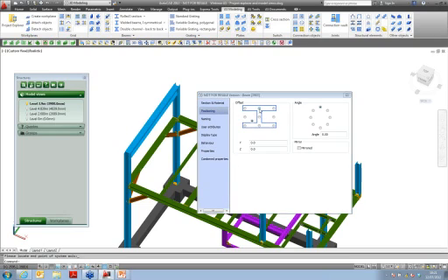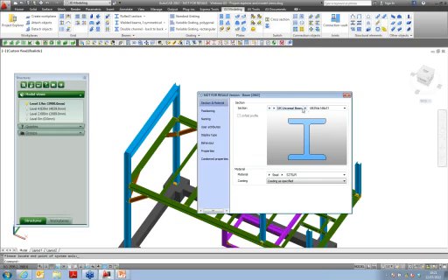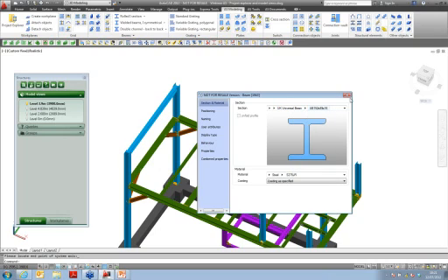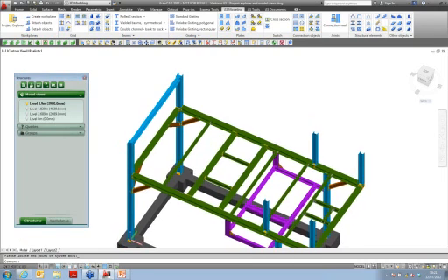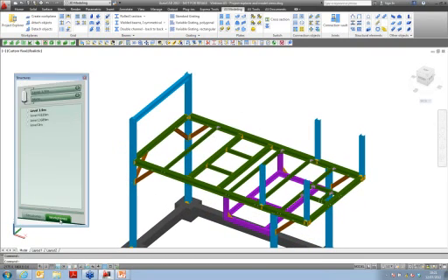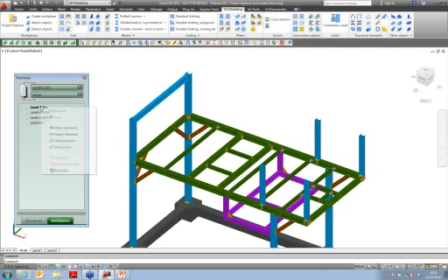You can specify its positioning like that. You can also specify the size of the beam, and here we go. We get the beam which is created on the right level. Something very interesting is the fact to go to the work plane, and with a right click you can decide to attach some elements. So I can decide to attach this beam to this level, and now I just have to pick some construction points to which one this beam will be attached.